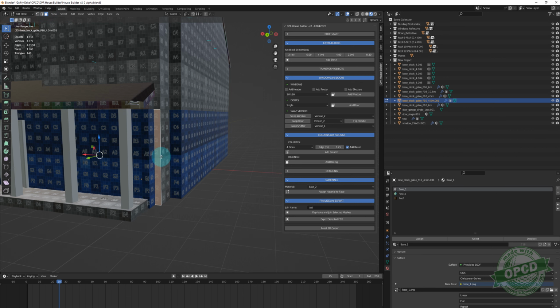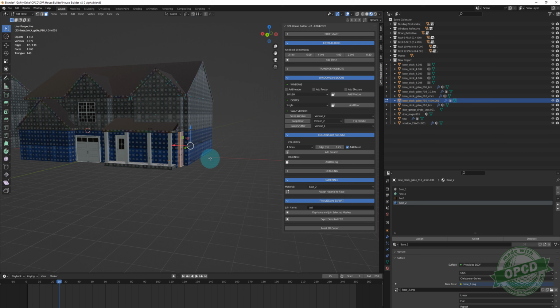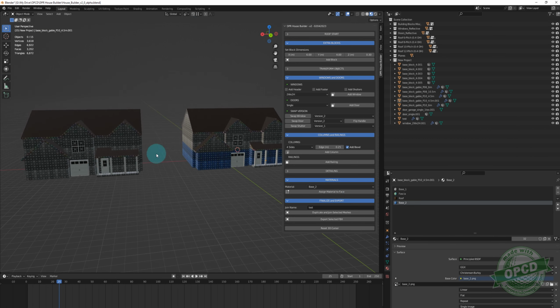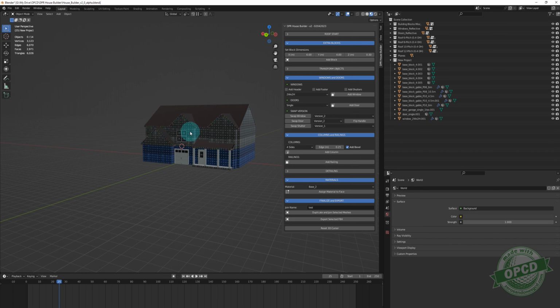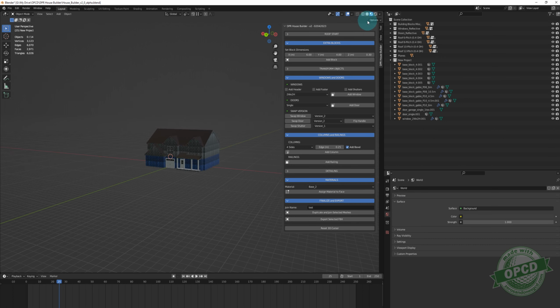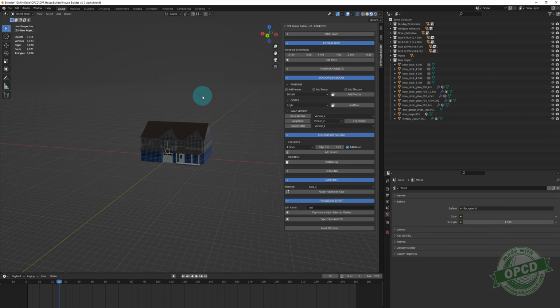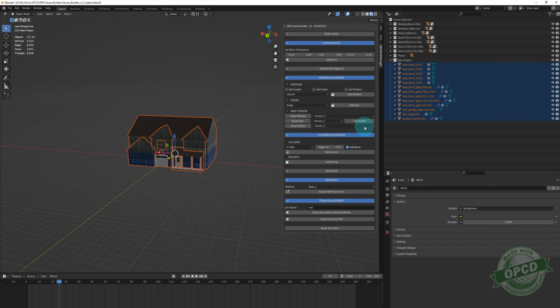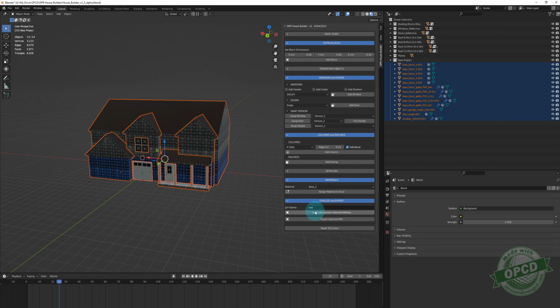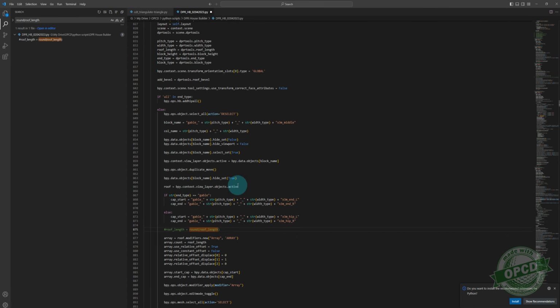Okay, cool. So I'm going to go ahead and delete this piece, and then we can make sure you're in X-ray vision, because if not, and I left click and drag, it may not select all the pieces. Let's just show you that. Yeah, it did anyway. You can see them all selected here. So duplicate and join. It didn't like that. I'm going to Control Z to undo it, and it crashed. All right, well, that's the end of my video for the moment.